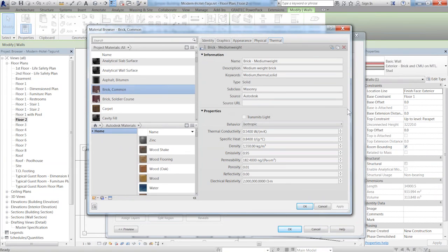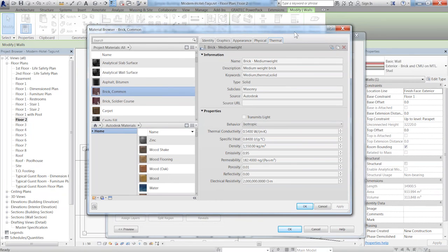So once you start building up and you're thinking you're just putting down lines that represent walls, it is far more than that in Revit. It's BIM built in. It really is. And all of this means that not only can you just export this information, this is where we can start using these tools on this Analyze tab up here as well, so that we can actually start figuring out how much heating is it going to need? How much cooling is it going to need? Depending on which part of the world it's going to be in. So your Revit model is ready-made, but of course, all of this information can be added to and changed and amended as you need it.